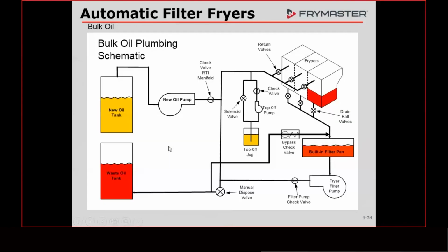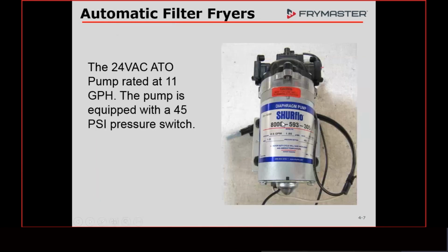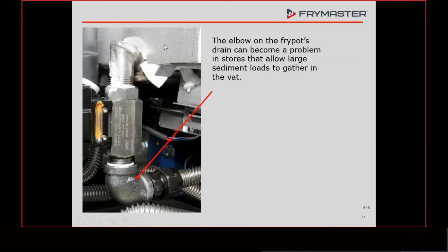Not just assuming nobody's there and they're not going to use it, because don't forget, automatic top off opens up this valve. These valves are down here at the bottom. Whatever oil is coming out of there is going to go in that manifold, and if you have that manifold breached or opened up, that oil is going to come back out on you.